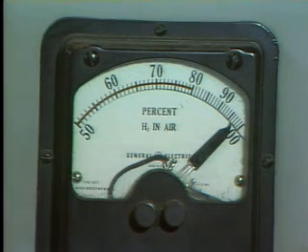The instrument that is used to monitor the concentration of hydrogen in the air inside a generator is called a purity analyzer. Purity analyzers are equipped with an alarm to notify plant personnel when the hydrogen concentration decreases below a predetermined value. The generator usually has to be shut down if the hydrogen purity level cannot be maintained.